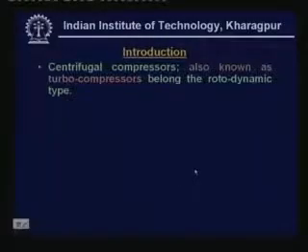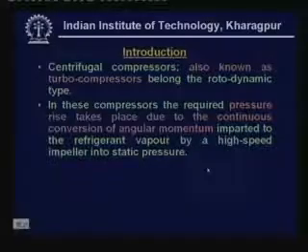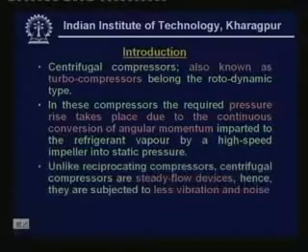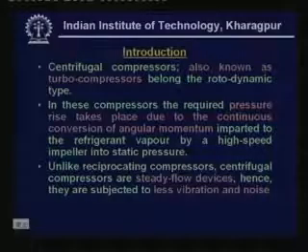As you know, centrifugal compressors, also known as turbo compressors, belong to the rotodynamic type. In these compressors, the required pressure rise takes place due to the continuous conversion of angular momentum imparted to the refrigerant vapor by a high speed impeller into static pressure. Unlike reciprocating compressors, centrifugal compressors are steady flow devices, hence they are subjected to less vibration and noise.